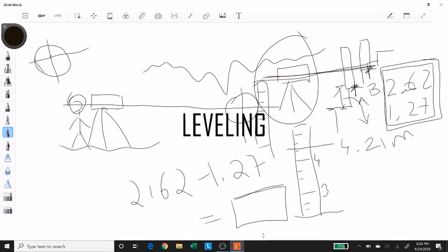And how do you get this? Because the leveling staff starts from 0, and if the line of sight remains the same, and the leveling staff at two different locations gives different readings, it means that the 2 points are at a different height. Had they been at the same height, you would have got the same reading on the staff at point A and point B. But since they give you a different reading and the level or elevation of your instrument remains the same for the two readings, that means the 2 points are not on the same level or same elevation.